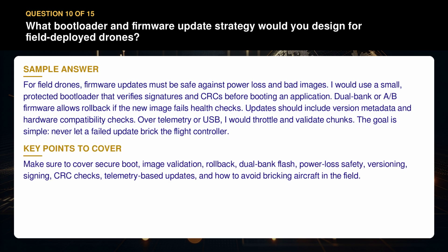Make sure to cover secure boot, image validation, rollback, dual bank flash, power loss safety, versioning, signing, CRC checks, telemetry-based updates, and how to avoid bricking aircraft in the field.